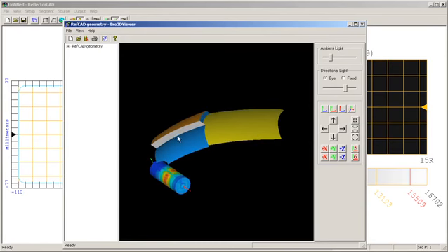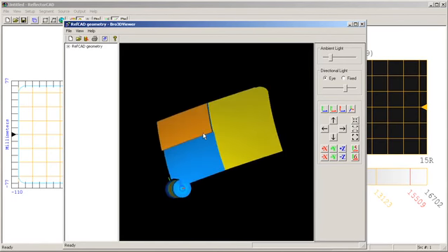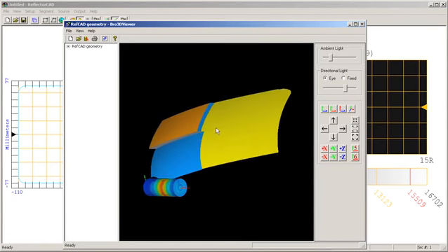First, this intersegment filler is much too large for production purposes. This intersegment filler over here actually has a direct path to the source, so light from the source can reflect off of or scatter off of that intersegment filler, causing a glare problem in the beam pattern. So what I really need to do is shadow this intersegment filler by these other two segments.